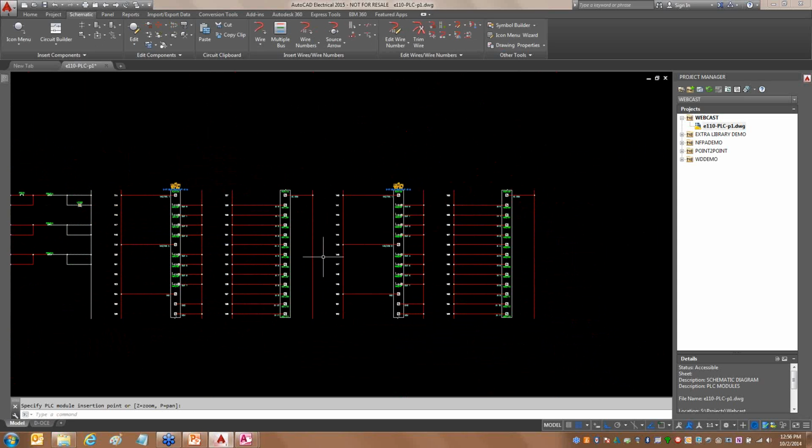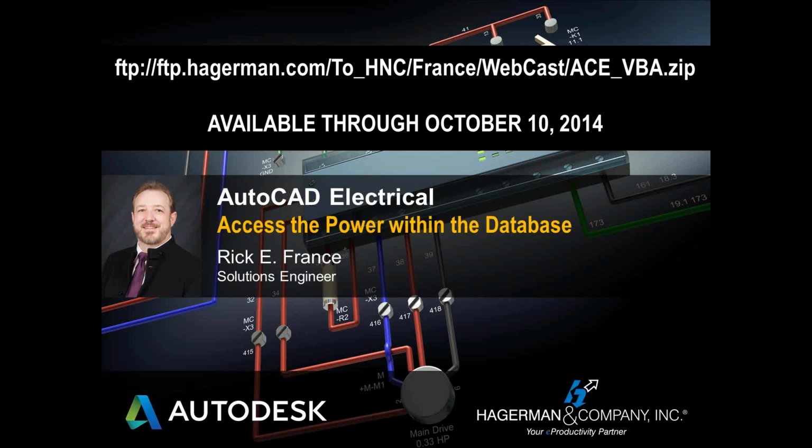So it's a nice little tool that will help you update that database with some things that you have that are global. You might want to, like I said, back up your system. Make sure that you try it out on some things because you may get results differently. One of the first things I did was when I was doing the pin list, for instance, I had my lights above my push buttons, and that caused some push buttons to get X1, X2 because of that. So sometimes it's sequence. You just want to test it and make sure you're right before you do it.